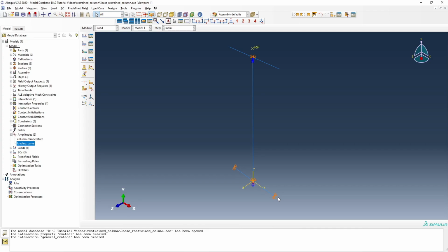Okay, so now for the initial loading step, we have applied this for the column and the end, and now we need to create these two extra boundary supports in the heating steps. Okay, so in the heating steps, let's first create in the spring node here, and then also we will create the upper plate left and right.